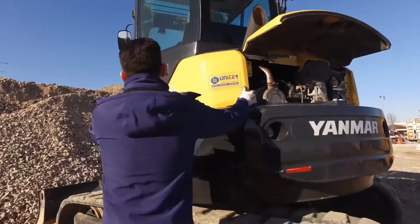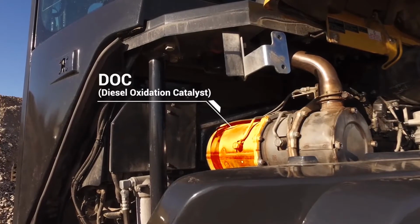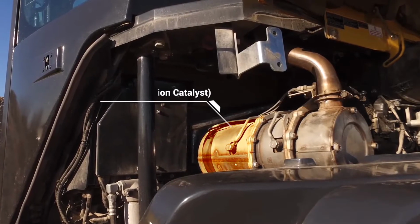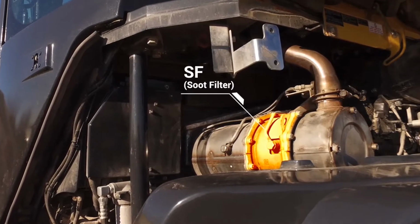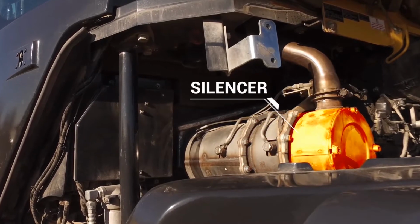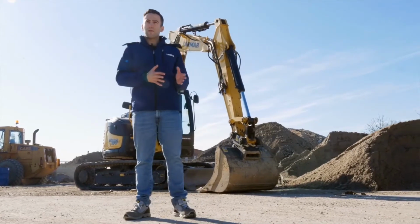The particulate filter installed in the Yanmar engines is made up of three components. The DOC, diesel oxidation catalyst, which eliminates the hydrocarbons and transforms the carbon monoxide into carbon dioxide and water. The SF, Soot Filter, which accumulates the residual exhaust microparticles. The silencer, to reduce the noise pollution. These elements can be replaced either separately or all together.